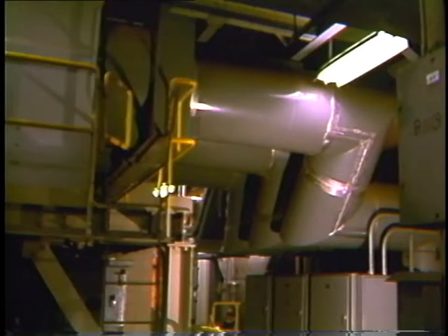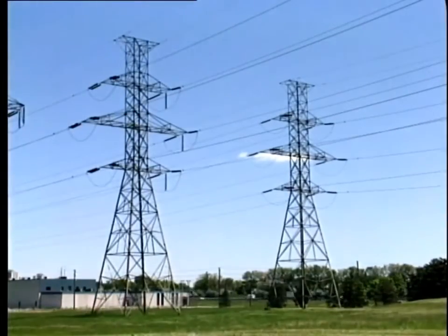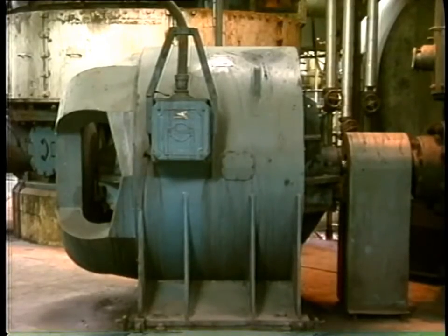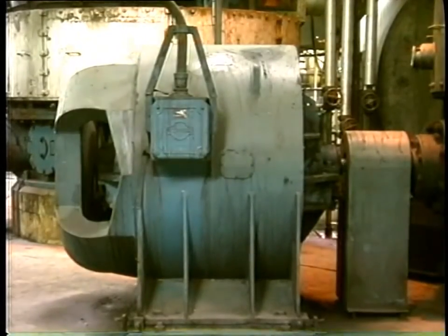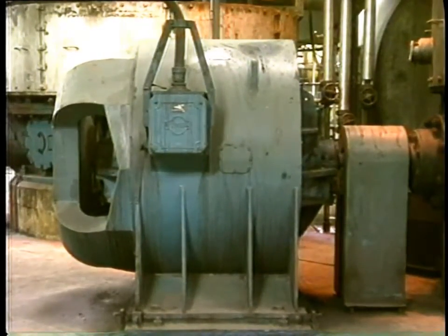The three outgoing terminals from the generator are connected by three lines to the three-phase load, that is, the bus or power transformer. This, in turn, feeds the three-phase power system. Most of the heavy loads on the system are actually three-phase balanced loads, for example, electric motors. Moreover, single-phase loads, such as residential loads, are connected to the distribution system in such a way as to provide an approximate balance.